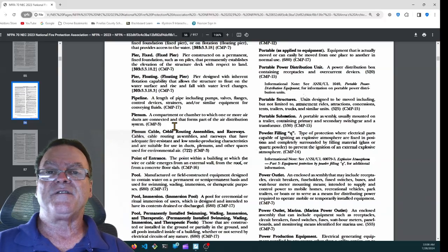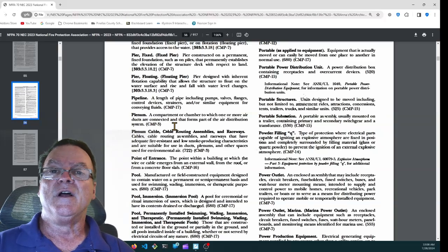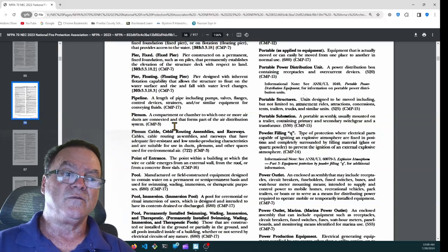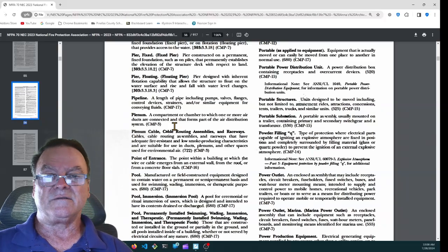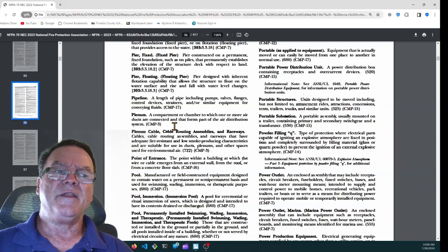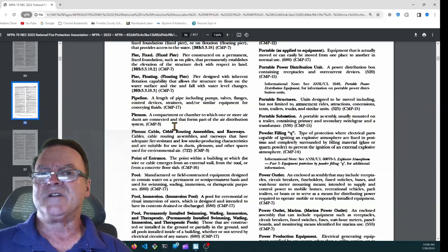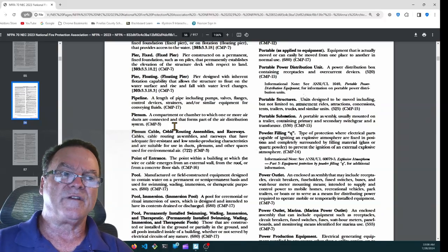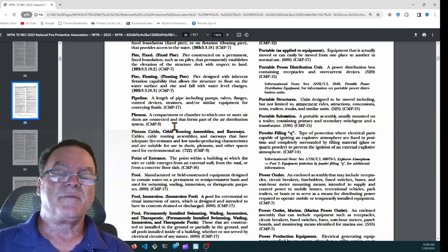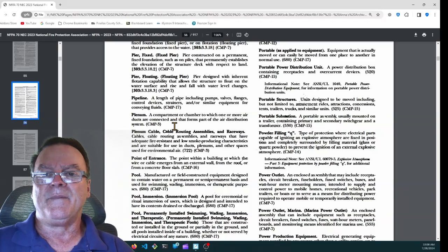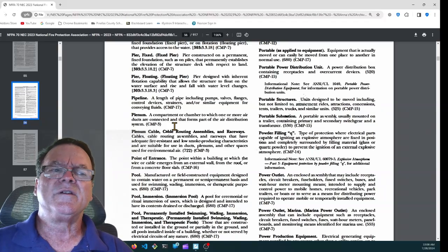And you don't want those toxic fumes spread throughout the building through the air system. So we have to use systems inside the plenum that are liquid tight flexible metal conduit or flexible non-metallic conduit, something that's going to keep them separated.